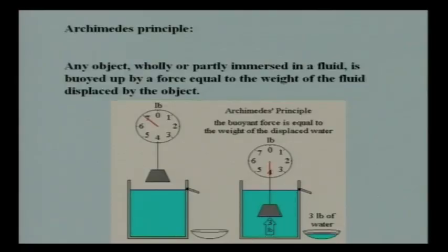the weight displaced, or some volume that we have, this is what this picture in fact explains more than what I can do. The weight displaced is equal to the amount of force that is acting upwards, and that will balance the weight of the body. Okay. So, the weight of the body is balanced by that upward force if it is remaining in equilibrium. If it is remaining in equilibrium, the weight of the body will be balanced by that buoyancy force, and that buoyancy force is equal to the weight of the liquid displaced. This is equal to this force, and this balances the weight of the body. That is the thing. Okay.